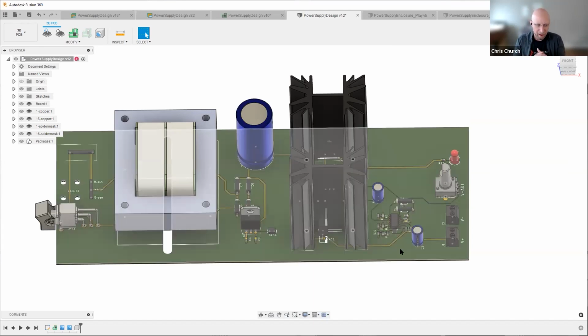So on the bottom, one of the questions that just came in right now, and this is very, very relevant here, is what size test points do we recommend? So typically for SMT, the minimum size we're going to want to deal with is 100 mils, 100 thousandths of an inch. That is very, very small. I would typically prefer them to be 2 or 3 times that size if possible, but we can fit a lot in there as long as they're a minimum size of 100 mil and have 100 mil spacing. We can go smaller than that, but the costs go up quite a bit.